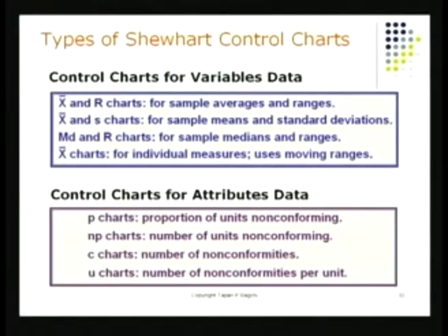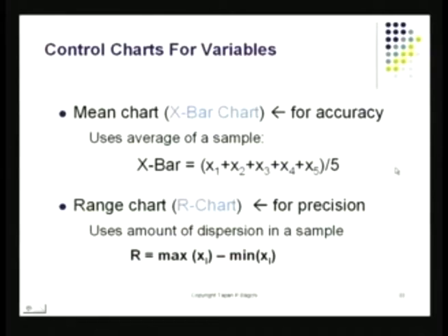Sometimes when you have to standardize things, you might use a lot of automation. But most of the time, we need not really have perfect standardization. We'll tolerate some variation there. And for that, control charts are just fine, because they are going to catch the exceptional situations. Same thing would apply to attributes data also. There we'll be using the P chart or the NP chart or the C chart or the U chart. And these displays show you exactly what kind of quality characteristics are going to be monitored. Okay, let's come back to the XBAR chart and let's try to see what we could do.